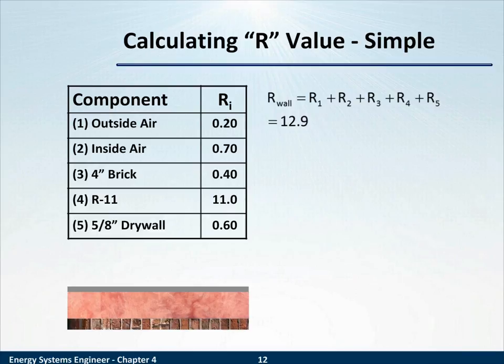One of the components of conductive heat transfer we looked at was the thermal conductivity. Well, the R value is the thermal resistivity. The R is resistivity. It's the inverse of the conductivity. So since we consider R value most frequently when we're considering the thermal performance or the conductive thermal performance of a wall, for example, let's look at how R value is calculated.